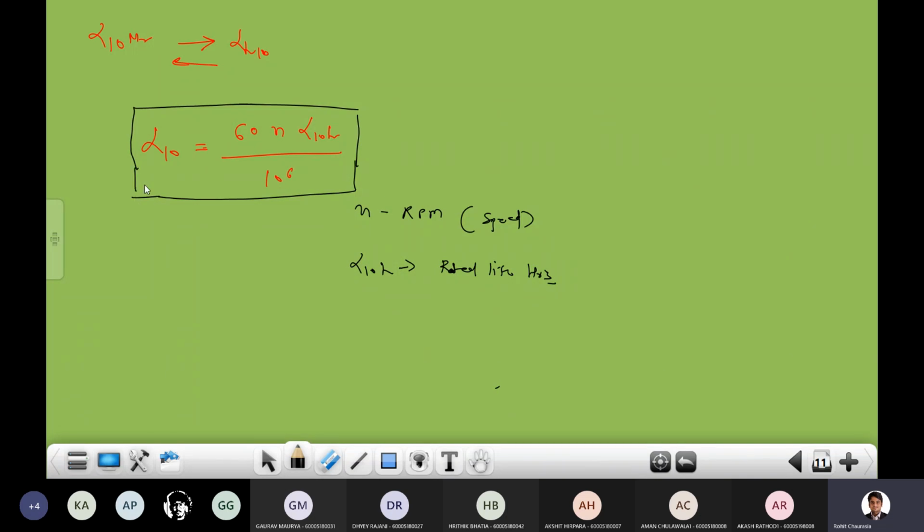From the first part or second part, ये हमको ये formula लगने ही वाला है. So after proceeding with this one, what is the important part? Already we have seen these 4 important formulas. First one is how to find out the life, L10 के respect में other life कैसे calculate करना है. We have already seen the equivalent load life relationship, and after that we have seen the conversion. That conversion is nothing but what? We have to convert million to hours or hours to million.